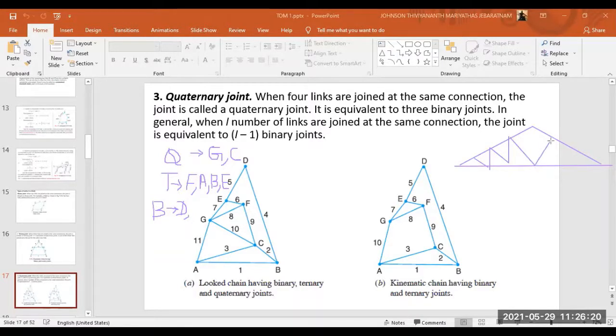This is in order to withstand the force from the members, right? So these are all kind of locked joints. These joints will not move, right? You can assume this will not move. What will happen if the joints move? The roof will move here and there, right? We don't want that, right? So these are locked joints, and these are three force members.